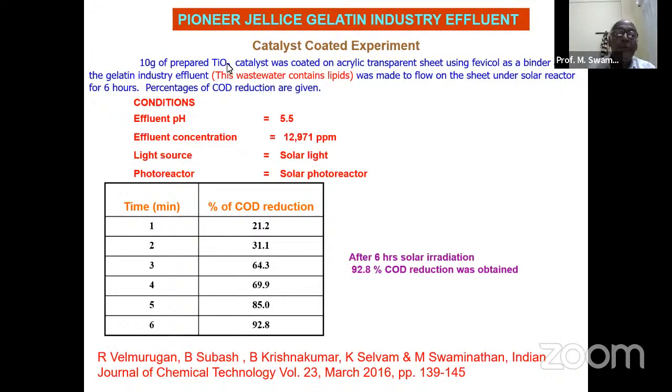So we have taken this effluent in our pilot scale photoreactor and used the prepared nano TiO2. We treated this one, and the percentage of COD reduction within 6 hours is 92.8. It was very efficient in treating this one. That is, prepared TiO2 was very efficient.